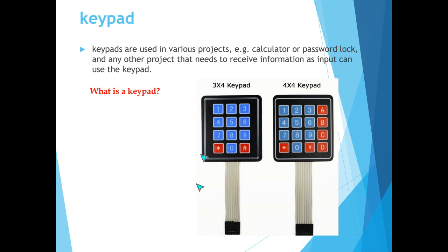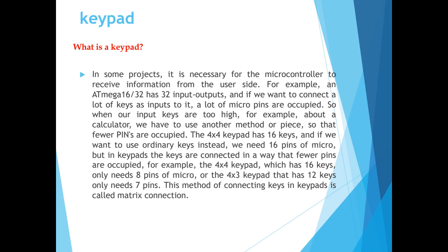But when we are using a keypad, the topology of a keypad is in a matrix structure, and for example in a 3x4 keypad, for interfacing with the microcontroller we need fewer pins, meaning that we need only 7 pins of the microcontroller to interface with it, and with a 4x4 keypad, we need only 8 pins of the micro instead of 16 pins for ordinary 16 keys.